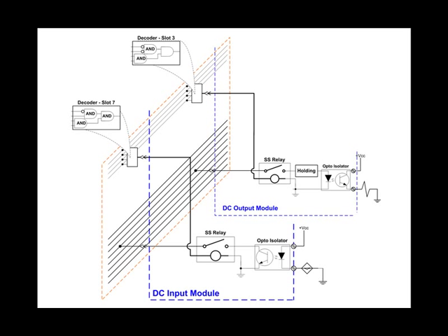It is sufficient to say that all I/O modules on the backplane are dumb as a brick. They do no thinking and no processing. They are simply no more than dumb switch banks that are activated one at a time to collect images of the states of groups of 16 inputs or outputs, and to collect other information or transfer the results of logic out to the actual output.